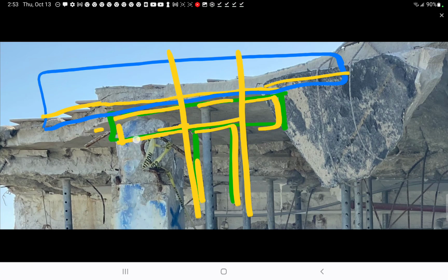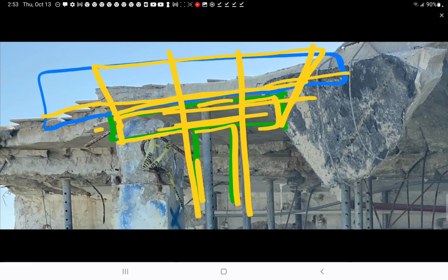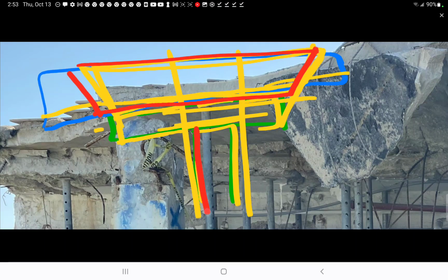It's rebarred at the top, number 5, and number 4 at the bottom. So it gets its own strength by default, by being married with the system now. Not quite composite, but yes, it will react with it. And so this becomes a new critical zone for the slab above. It gets elongated. It's longer than that, I believe. So let's do something like that.